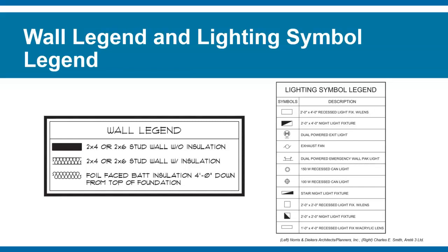Let's say the drawing you're looking at is in 1/4 inch scale. Then you just find the 1/4 inch scale mark here, and then you can read it. The numbers that represent 1/4 inch apart also represent a foot in length of what you're reading.